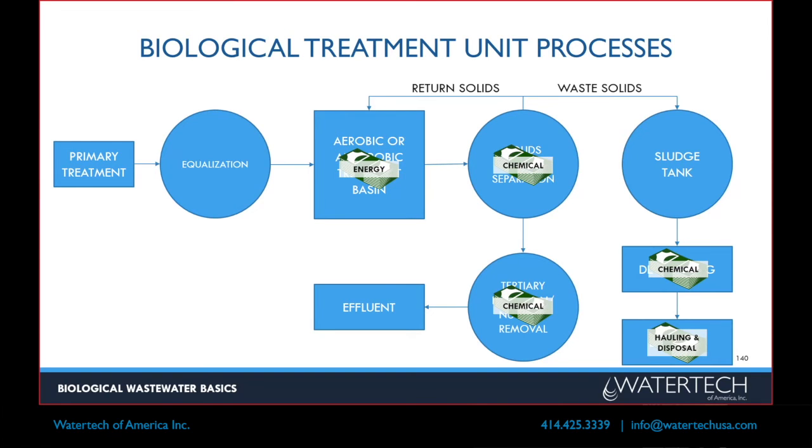Lots of the time they're ultrafilters instead of actually reverse osmosis membranes. But it's a physical barrier. So you can have things go to crap here, but since you have that physical barrier, you can still run without being at risk of violating your permit.